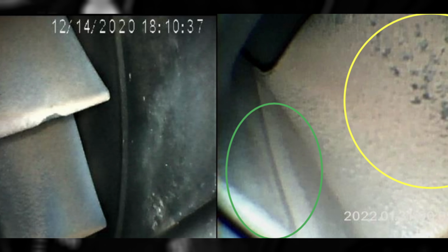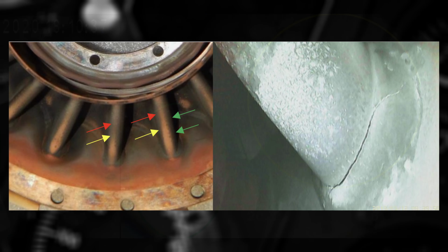Most of the time, as was the case with these, what appears to be damage, cracks, or flaking are actually borescope tracks through the dirt or chunks of accumulated contaminants that have flaked off within a very dirty air path. These engines are perfectly serviceable, but very dirty. Do yourself a favor and clean the air path prior to inspection with the borescope. The air path cleaning and inspections by borescope work together as a team.